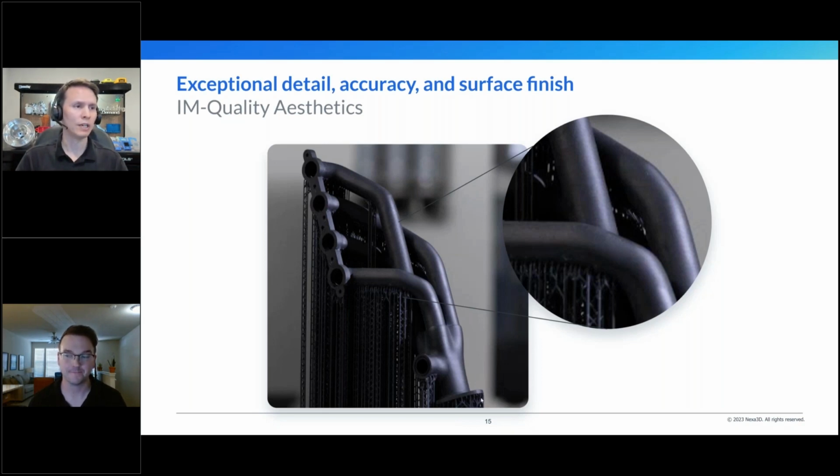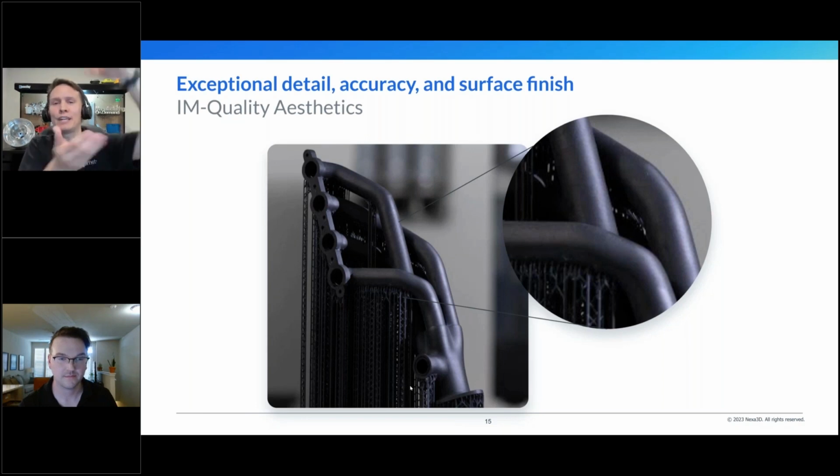So they're very versatile. I also want to point out here, because when we talk about design tips, we're going to be talking about support structure. If you imagine this is built upside down, like it's coming out of the vat when it's being built, any overhanging features do have support structures, so that's what these fine lattices are.